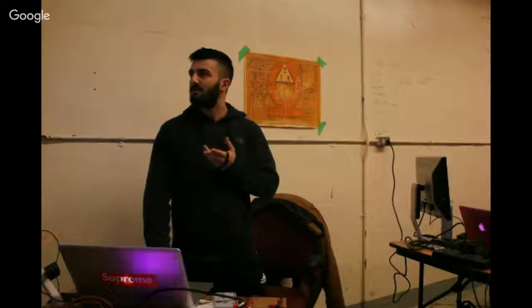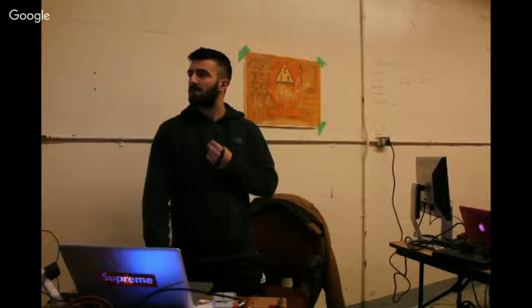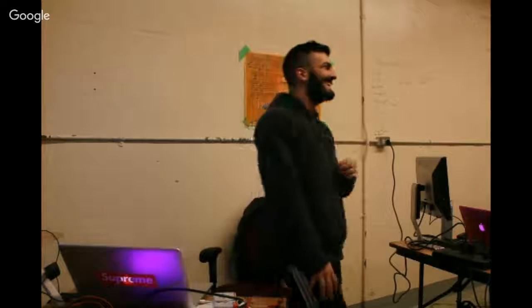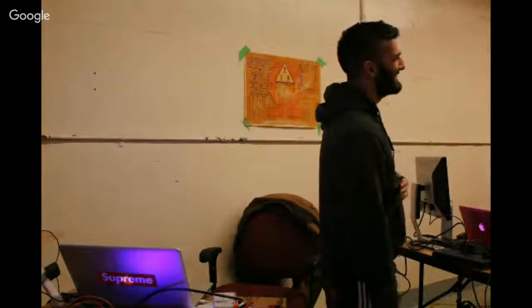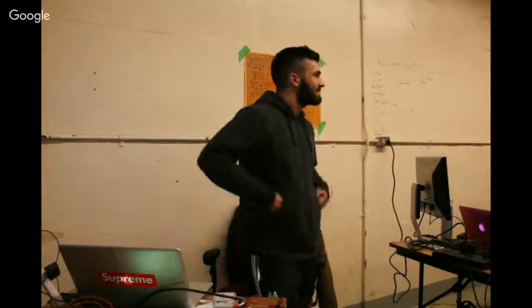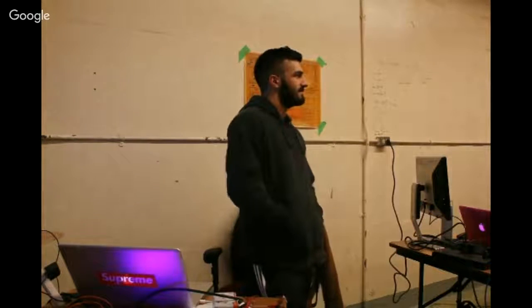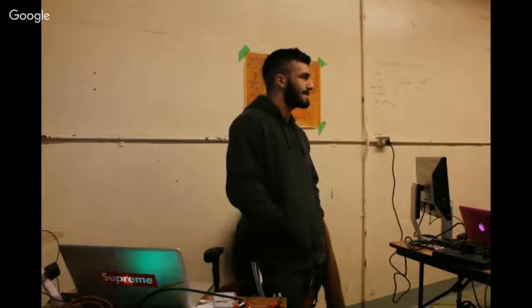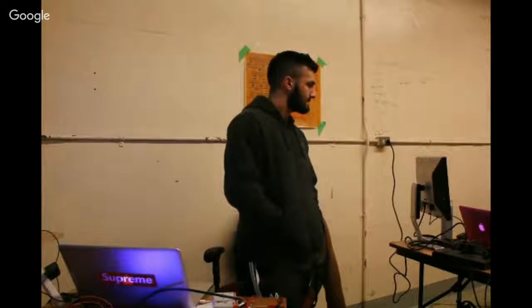At some point in here, talk about the problem we had with the relay too, because that was quite interesting. There were multiple problems. You think that when you use the relay, it's just like a switch: you give the low voltage DC input signal and the high voltage turns on. When it's not turned on by the low voltage, you just get nothing, no connectivity across the high voltage terminals. In fact, that's not the case.